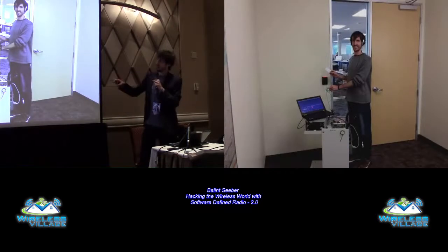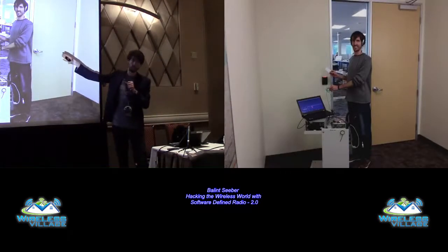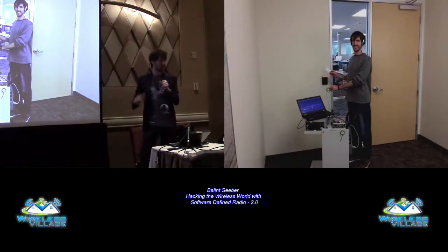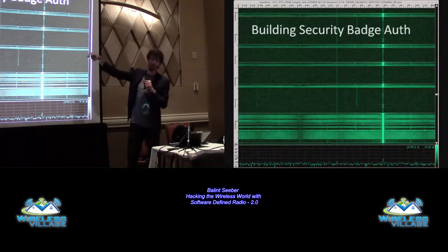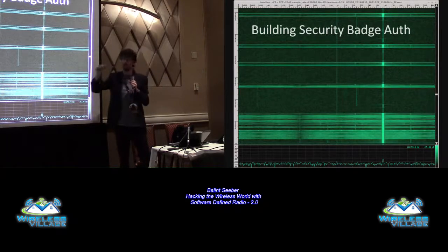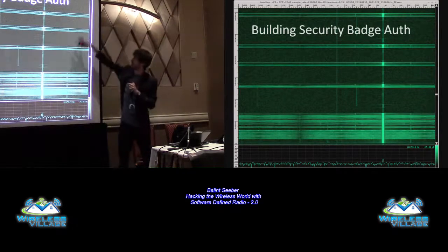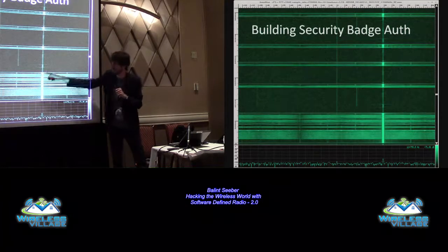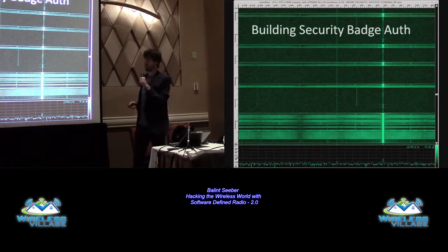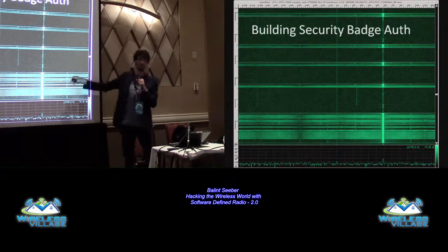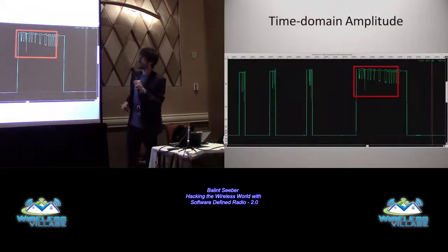The final thing with RFID was I just had a quick look at using the badge system in our building. This uses essentially backscatter as well. You have the chip in the card, and then every so often the reader will send out this broadcast, this interrogation, which is this periodic thing here, and then below you see that the card then replies. It has a chip in there, it has an antenna that changes the characteristics, and it'll read out the data there. So that's what's happening here.